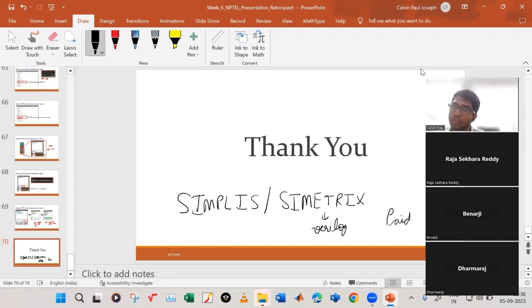One suggestion would be, see, all these Texas Instruments and other companies, they have reference circuits of a buck converter, which they have made. Okay, they will be using their own controller. Instead, you can use the power stage, that is the inductor, capacitor, load resistor, all of those from those manufacturers, but as a controller IC, you can use an FPGA.